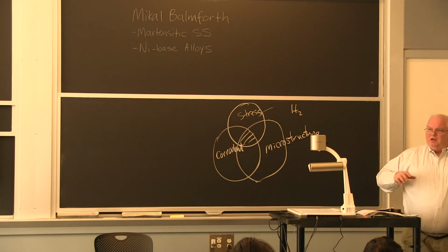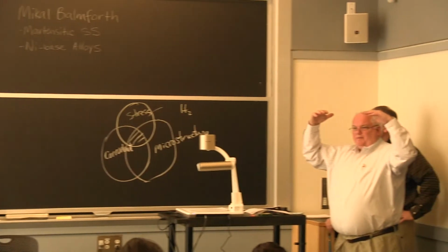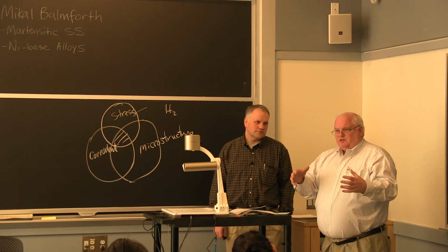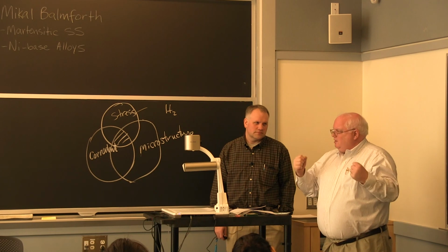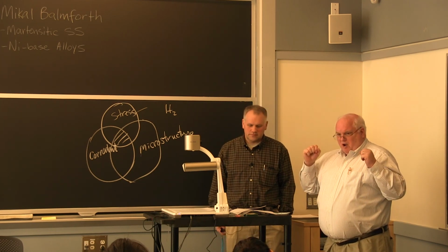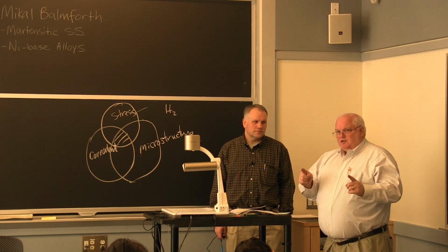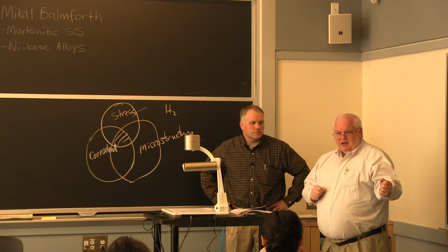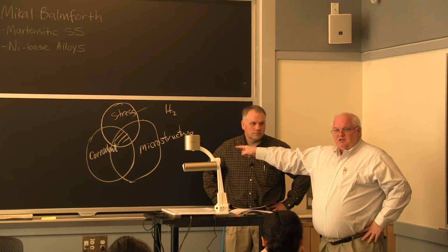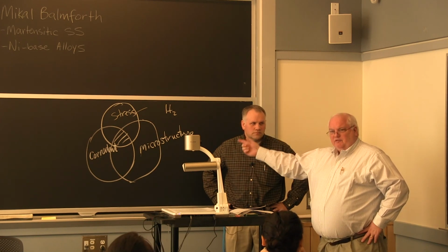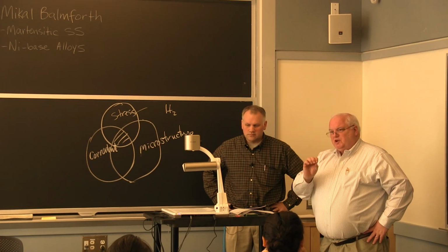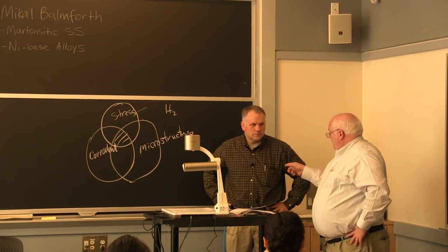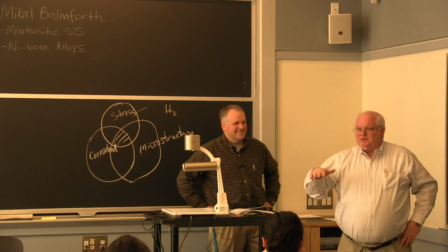So in a sense, the Venn diagram on a high level is a form of stress corrosion cracking, and you can think of hydrogen embrittlement as just a subset of one form of stress corrosion cracking. I will tell you that in the scientific literature, metallurgists throw hydrogen embrittlement and stress corrosion cracking together 70% of the time. There is a difference. I don't know if I told you this year, but certainly last semester I mentioned several times: the difference is one occurs at the anode and one occurs at the cathode. Why? Because the corrodant is hydrogen, which is positively charged. In chloride cracking, it's chlorine that's negatively charged. So you can distinguish stress corrosion cracking from hydrogen at one level, but most of the time they just throw it all together. And so in a sense, the Venn diagram I showed you yesterday, so yes, I did cover stress corrosion cracking yesterday, but only a subset of hydrogen.